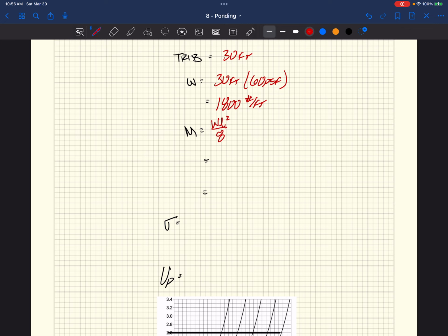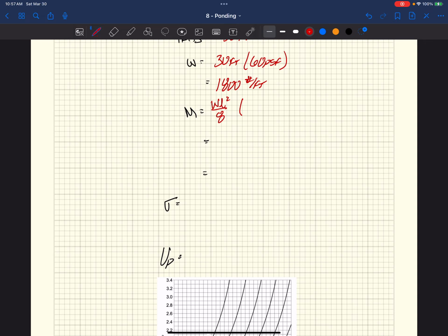With 7 point loads, you can actually look in the steel manual. They have an equivalent uniform load chart that allows you to take a point load and come up with the equivalent. When you get up to 6, 7, 8 point loads evenly distributed along the length, you're getting really close to a uniform load. And we're assuming that it's uniform for this analysis method anyway. So I feel pretty confident about the uniform method. We're going to say this is the assumed approximate uniform.